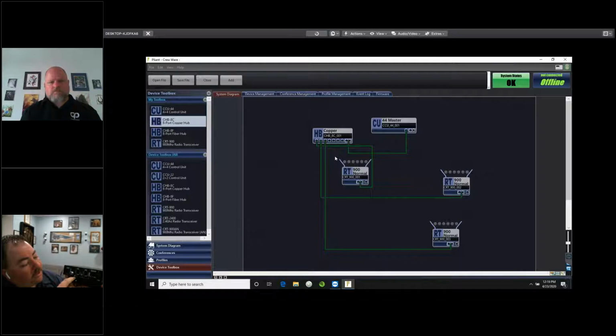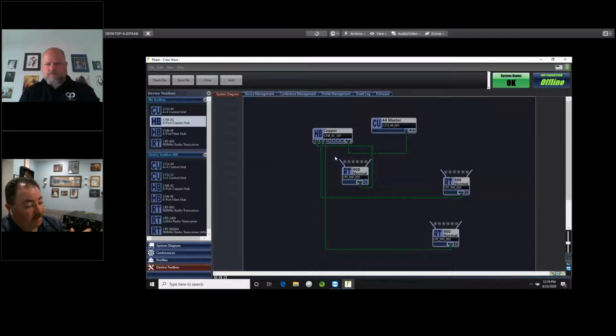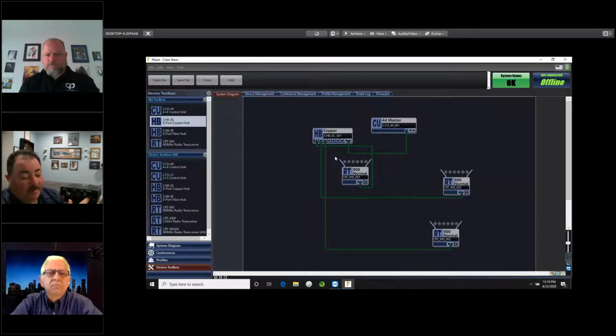Your CrewNet LED lights down here will flash when it sees the network. However, unless it's an identified device and knows who it is, the transmit and receive LED lights will not light. So once you connect it to a valid port, you'll see these 2 lights light up, and it'll give you an indicator that it's on the network and it knows who it is.